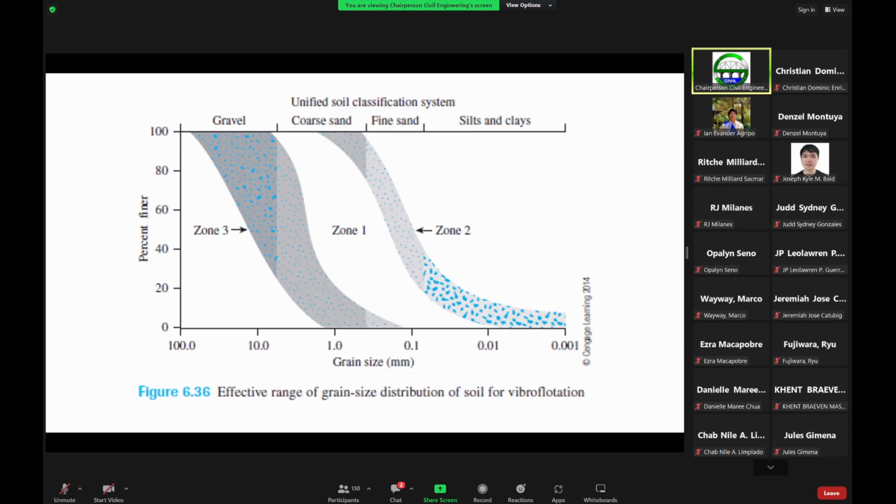We had one project before wherein we tried to check if we can still do vibro compaction, because it's always cheaper as compared to the stone column approach. But when we tested the soils and did a CPT test in the field, we found out that the fines content was way beyond the allowable for the vibro flotation or vibro compaction technique to be considered effective in achieving a denser material, because we were dealing with loose materials up to depths of 10 meters, wherein it's already possible to use normal compaction equipment.